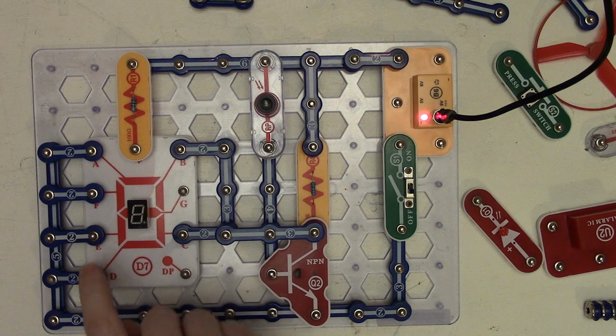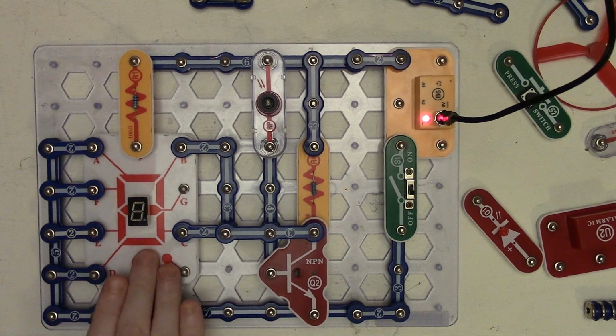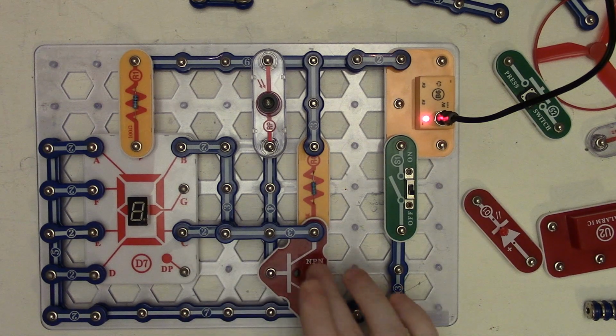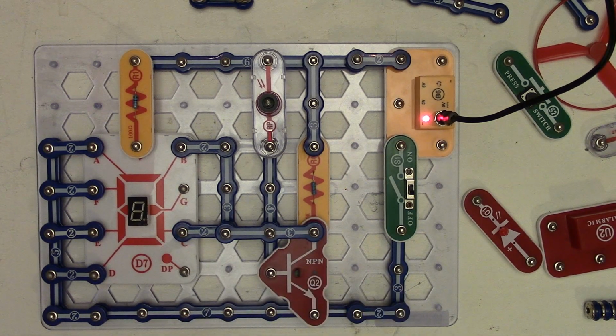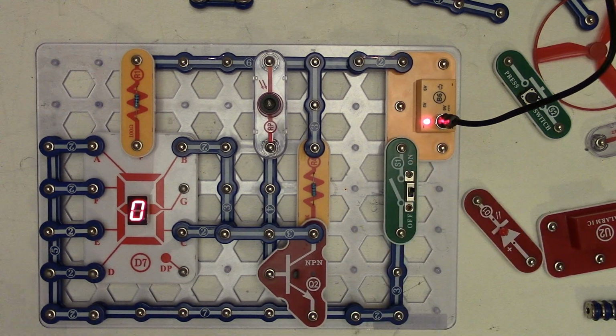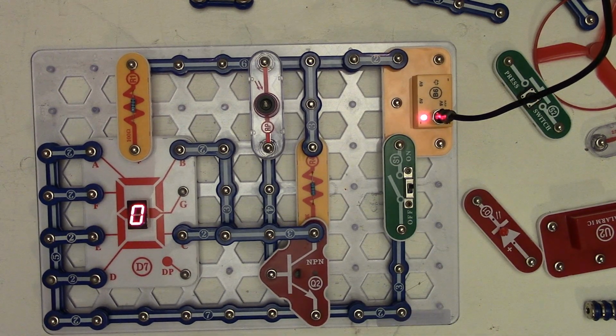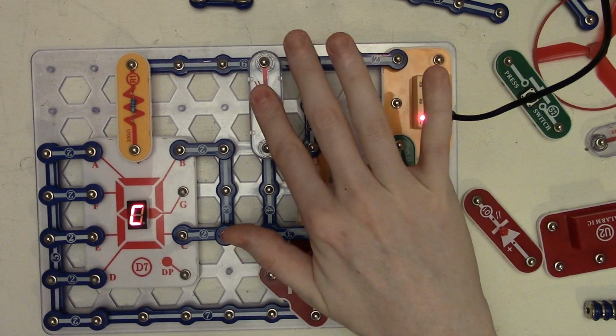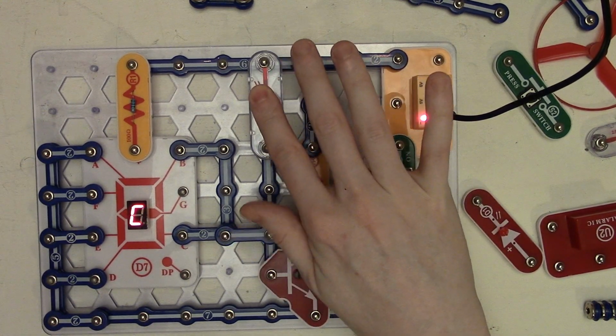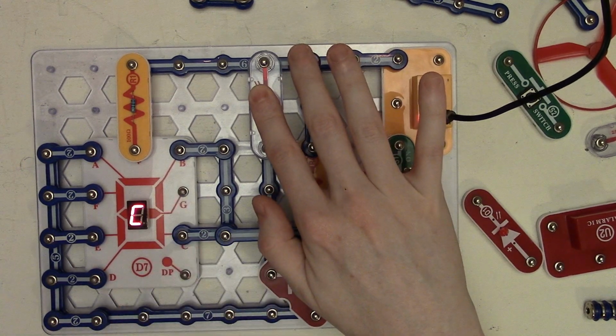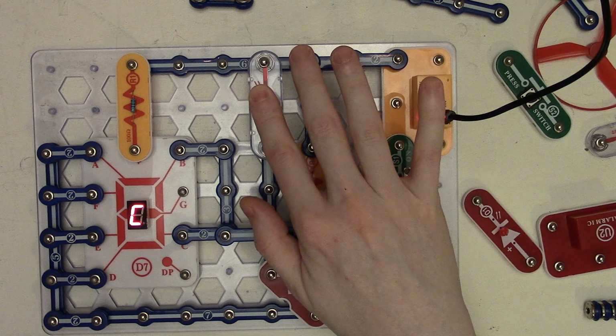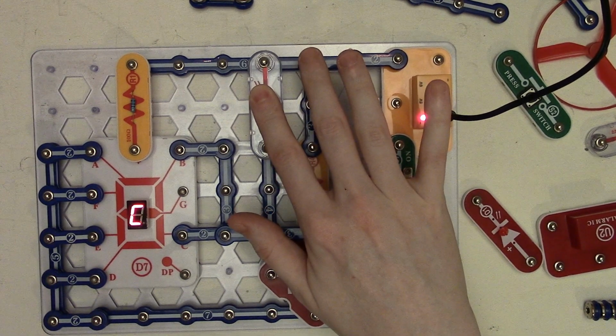So A, F, E, and D are constantly on on the 7-segment LED, and then B and C are turned on and off via our NPN transistor there. So when we turn the circuit on, we have the letter O being displayed on our 7-segment LED, displaying that, okay, something is open because the photoresistor is seeing light there, allowing the NPN transistor to be turned on. Now if we cover it up, we take current away from the transistor, turning off segments B and C. So now it displays the letter C to say, oh hey, the door is closed, because it's not seeing any light.